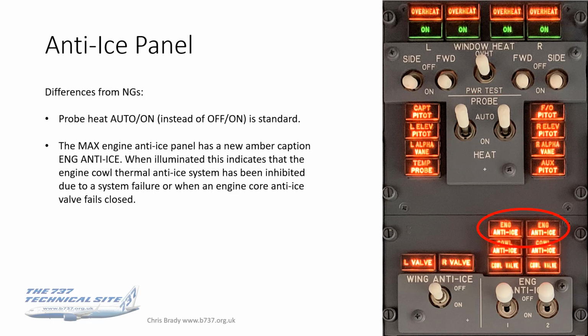The Max engine anti-ice panel has a new amber caption of engine anti-ice. You'll see it down there, highlighted by my red oval. When illuminated, this indicates that the engine cowl thermal anti-ice system has been inhibited due to a system failure, or when an engine core anti-ice valve fails closed. And by system failure, what they mean is, again, the AASI. This is possible because of those controllers.